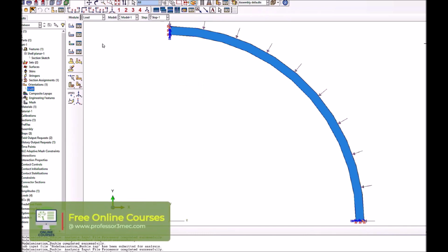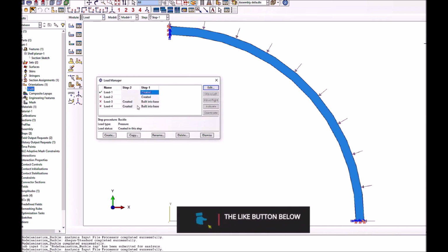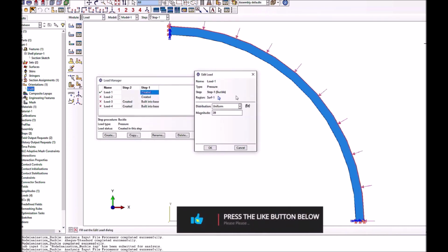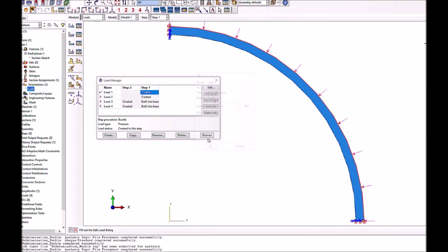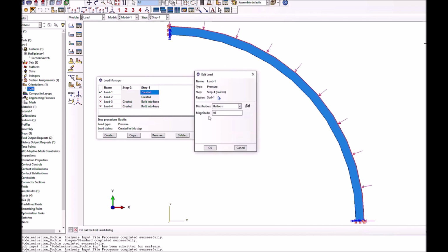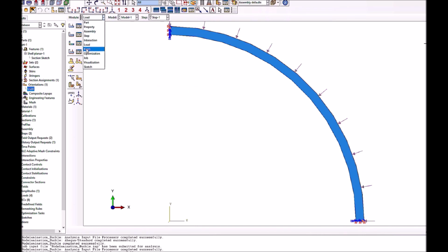So this is the loading. I also have to apply pressure, so I'm applying external pressure, which is 40 megapascal, which is the depth at which it was there. If you remember, in one of the parts, I gave you the equation to compute the pressure at a certain depth of the sea. Based on that, it's around 40 megapascals, so I'm using 40. Again, this doesn't matter here. You can also use 1 megapascal because this is just a linear buckling analysis. But in reality, it was like that. So this is done here.